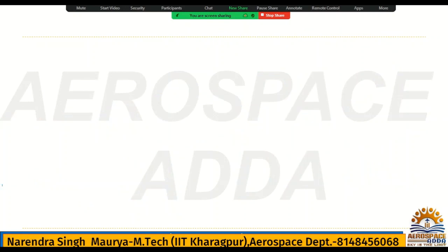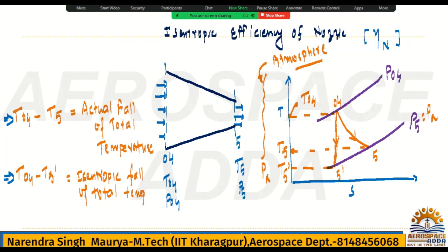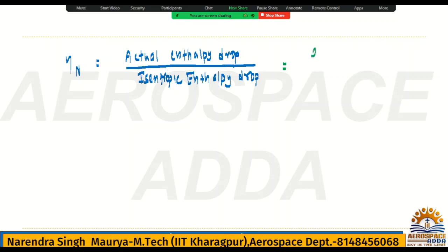Now, what is the nozzle efficiency? Nozzle efficiency is nothing but the actual enthalpy drop divided by the isentropic enthalpy drop. Okay, so how to write this? What is the actual enthalpy drop? See, actual enthalpy drop in terms of enthalpy you can write H naught 4 minus H 5, divided by H naught 4 minus H 5 dash.